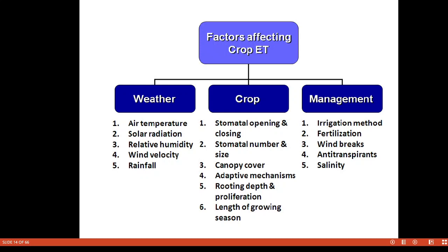In higher rainfall periods, you expect higher evapotranspiration, higher evaporation, because water is readily available on the surfaces than outside the surface. So even with small wind blows, small solar radiation, and also low air temperatures, moisture is still evaporated into the atmosphere during the rainfall seasons.